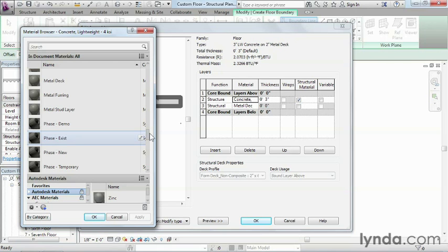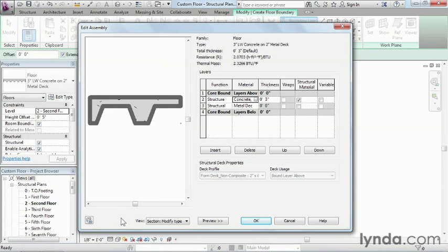and then that floor would be built out of that material when we model that floor in Revit Structure. Now I'm going to go ahead and click on Cancel in this dialog box in order to get out of it. There's also a function feature here, and right now it just says Structure, but you can see that there are different layers of material, and usually whenever we're dealing with this, it's probably always going to be Structure for floors.